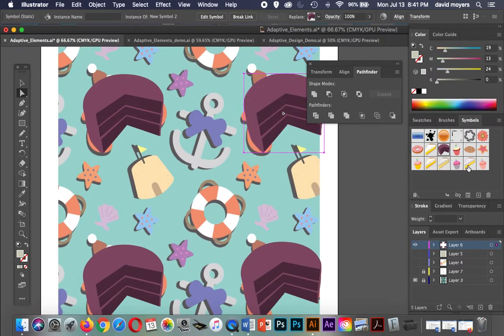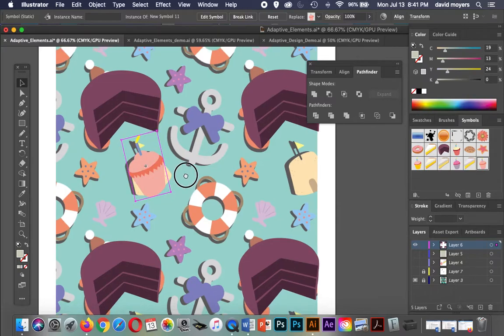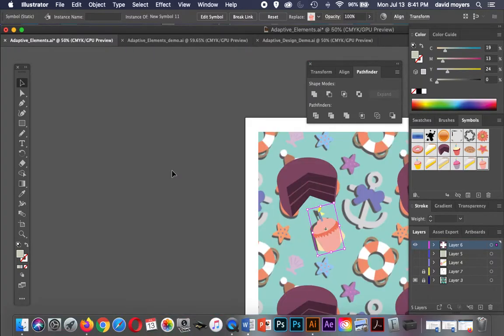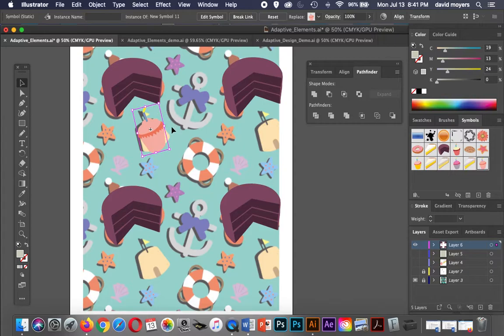Okay, so I'm going to drag over my last cupcake I just made. Now, we can rotate this a little bit, or we can rotate as a symbol later, but I'll just rotate it now, and we'll duplicate, because one of the things is these symbols are all linked to the main symbol that comes out of the palette. So if you do something like this where I'm copying it, I start dragging it, hold down the Alt key, and then copy it. That still is linked to this symbol in here.